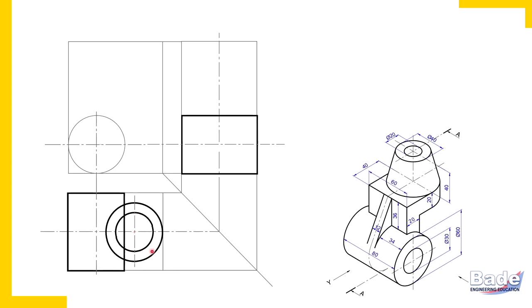And watch here, this is top circle. So base circle and this top circle, top surface boundary we have drawn here. And now we'll draw this cone in the front view. It is topmost portion of the object. So draw end projector. Here it is top surface and base surface. And this is how that cone or frustum of the cone is ready.